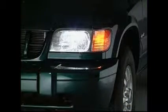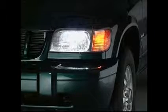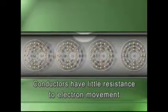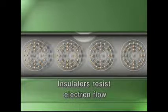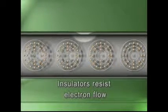Resistance is defined as any force or substance that restricts or opposes the flow of current in a circuit. In every atom, the electrons resist being moved out of their orbits. The amount of resistance of the electrons to being moved depends on the structure of the individual atom. Conductors, as we saw earlier, have little resistance to the movement of their free electrons from their loosely held orbits. Other substances have a greater resistance to the movement of the electrons on their outer shell as the electrons are more tightly held to the nucleus.